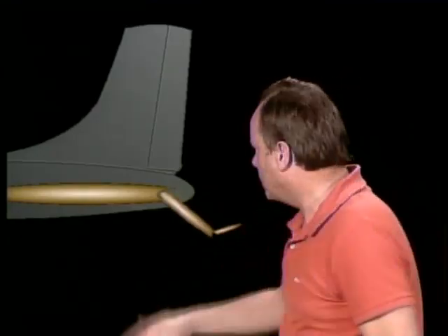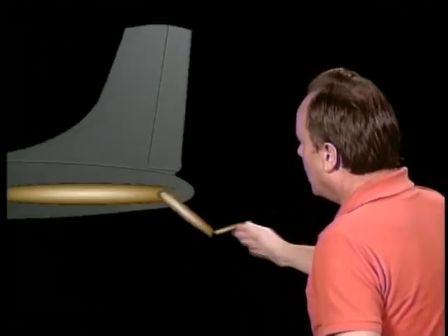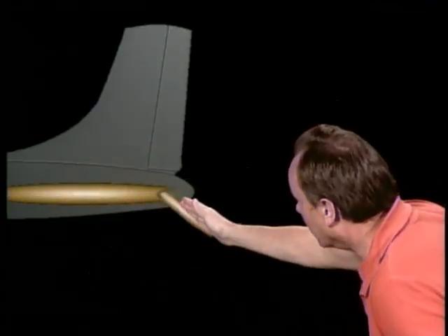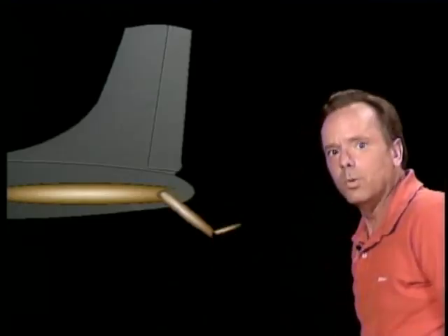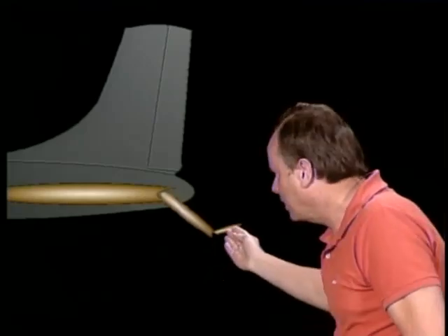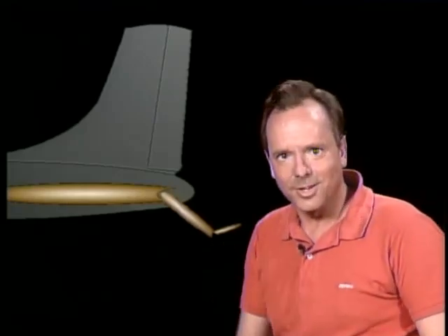Now let's assume as a mechanic you're making an operational check of the trim control system, and you move the cockpit control towards the nose down position. They're going to ask you on the test, what's going on back here at the tail of the airplane? Well, you want the nose to go down. That means the tail is going to go up, the elevator is going down. That means the trim tab will go up. So here's the question and the way it will read on the FAA written exam. Movement of the cockpit control towards the nose down position during an operational check of the elevator trim tab system will cause the trailing edge of the trim tab to move upward regardless of the elevator position. And that's what you need to know for the test.